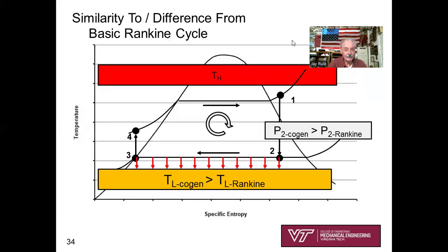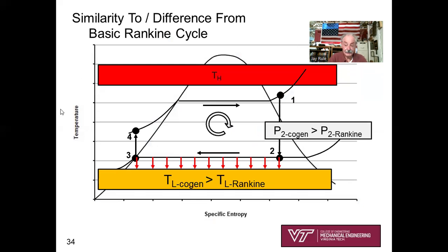Now, there is a little subtle point here. In the wintertime, where Virginia Tech wants that heating steam, you recognize that coming out of the turbine, it has to be pretty hot steam, doesn't it? And so it turns out that your pressure is not going to be down at the condenser pressure. It's going to be at a higher pressure. It's going to be a pressure higher than 1 atmosphere.